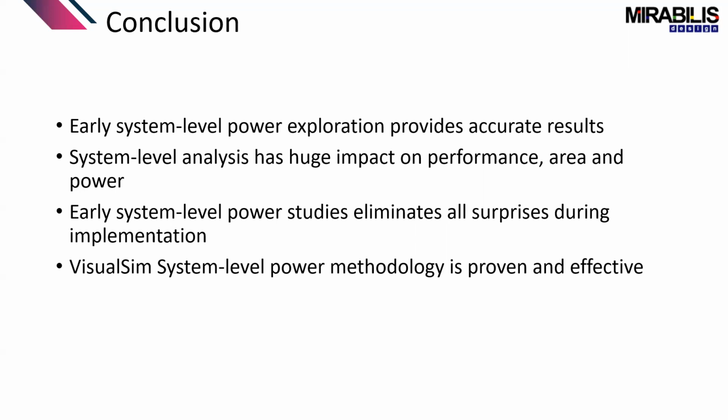For our specific use case, the multimedia SOC, we could see that with the hardware accelerator added to it, the area was increased as well as the power consumption went above the threshold. So we were able to accommodate all of these surprises by using the simulation platform's early architecture evaluation. The VisualSim system level power methodology was proven and is effective for different similar situations and use cases.